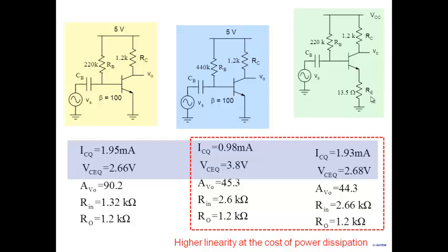And the other thing that you obtain is high linearity. This circuit gives you high linearity, reduces harmonic distortion. Now, if you compare these two stages, look at these two. Both these stages give you same gain, same input resistance, same output resistance. And I'm saying this stage gives you higher linearity, lower harmonic distortion. Well, remember a general statement, something has to come at the price of something else. You can't get it for free. Apart from the fact that I've used a small resistor here, so I've used an extra component. Note the difference between the two. Same gain, same input, same output.